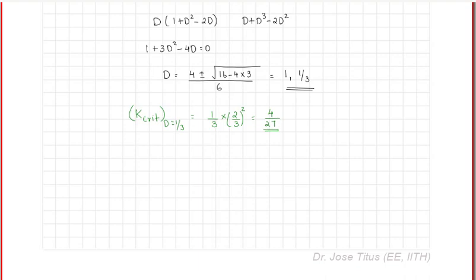So the similar reasons which we set for the buck converter in order to not operate in DCM mode, or the advantages of CCM mode over DCM for the buck converter, similar reasons apply equally well for the boost converter also. So most of the time when we design the converter, we will try to make sure that the converter is operating in continuous conduction mode.